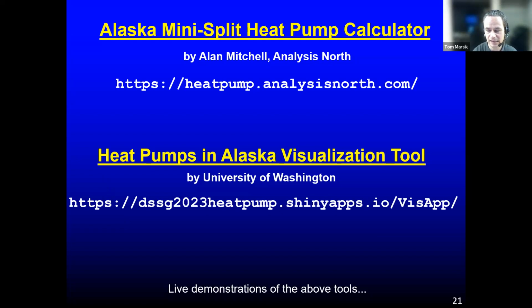And the reason that an electric space heater has a COP of 1, which means efficiency of 100%, is that there is no connection to the outside environment. There is no outdoor unit like a heat pump. There is no chimney. So from the law of physics, we know that energy cannot be created or destroyed. In other words, energy in equals energy out for that space heater because it has no meaningful storage in it. So all the electrical energy you put into it ends up coming out in the form of heat. That's why it is 100% efficient.